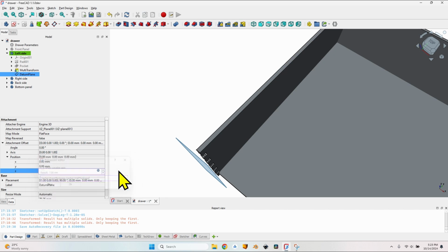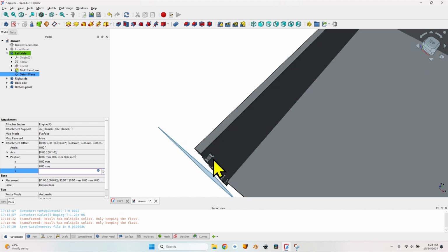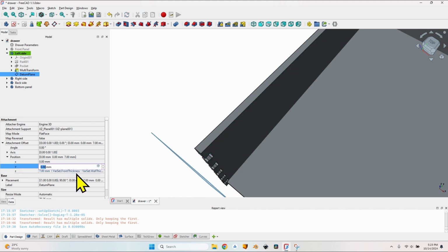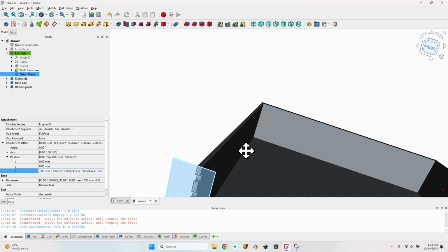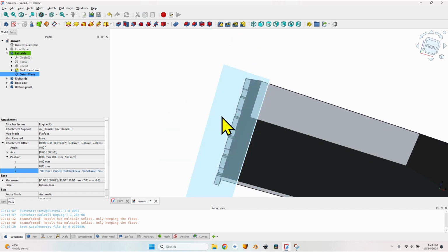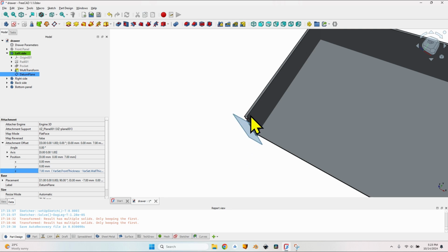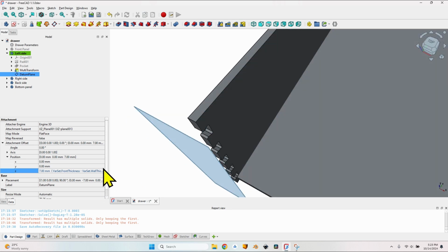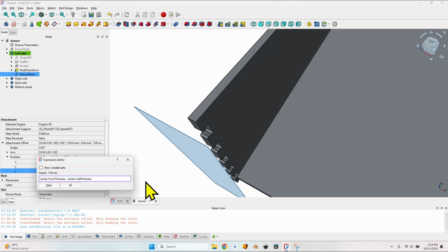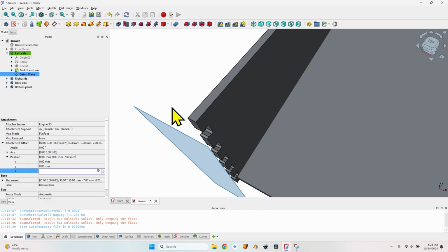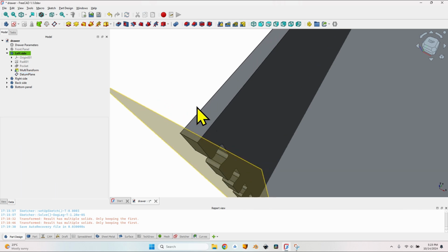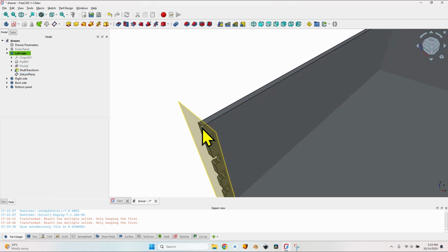And now the datum plane should be touching this face. Well, it is not going to be. As you can see, it moved the other way because the datum plane has its top view set like this, so any positive value on the Z is going to move it upwards. If I want to move it to the back, I'm going to have to multiply this with -1 multiplied, and I will use parentheses because I will also modify this formula. Press on OK, and now you can see it is glued to the top of this face.